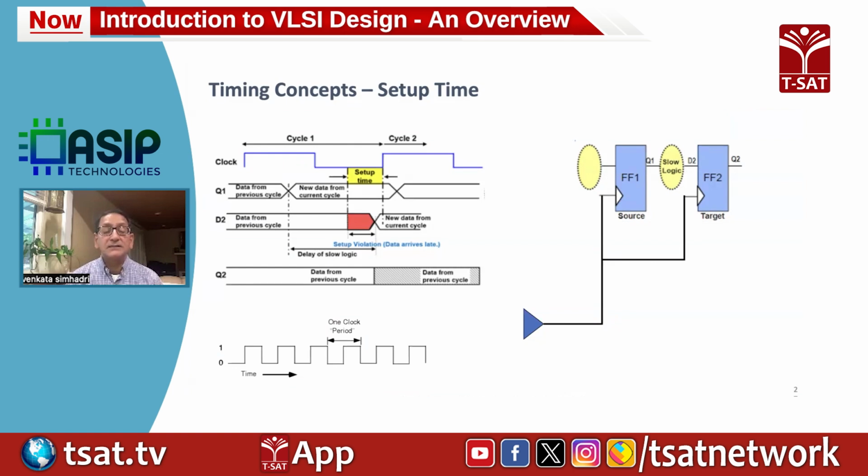And the most important thing is the speed at which the design will be running. So let's say you are designing a chip that's running at 1 gigahertz, then you define your clock with a clock period that meets that requirement. And after converting that gate level netlist into a physical design, the physical design will have the interconnects between these gates, and that will introduce parasitics, and it will introduce delays between the gates.